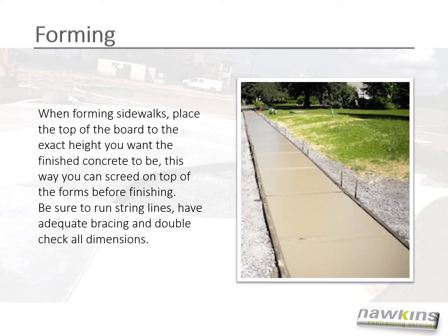Forming. When forming sidewalks, place the top of the board to the exact height you want the finished concrete to be. This way you can screed on top of the forms before finishing. Be sure to run string lines, have adequate bracing, and double check all dimensions.